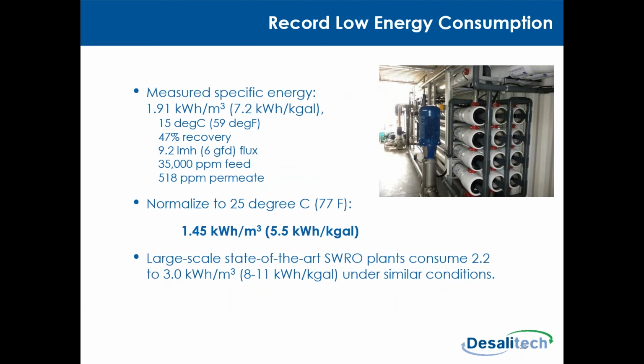All right, so let's talk about a specific example, operation of a Desalitech system under low energy conditions, but in typical conditions for seawater. So what we did was we operated at 47% recovery and 35,000 parts per million. It's close to seawater.